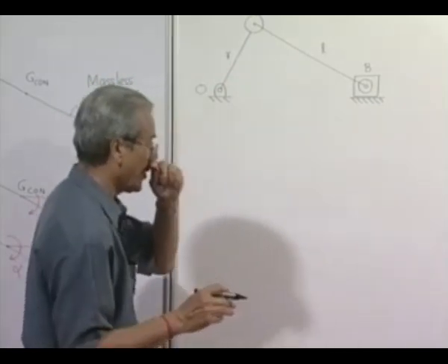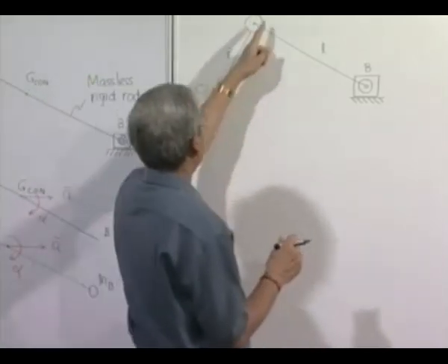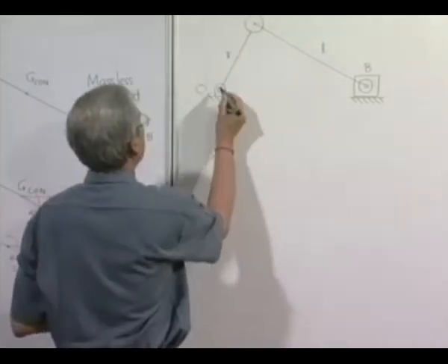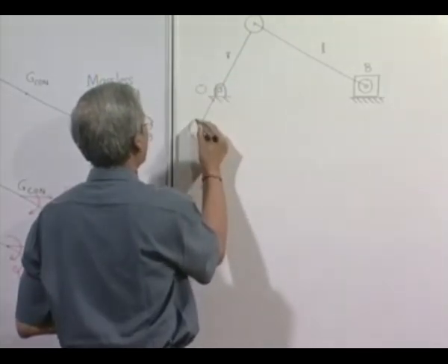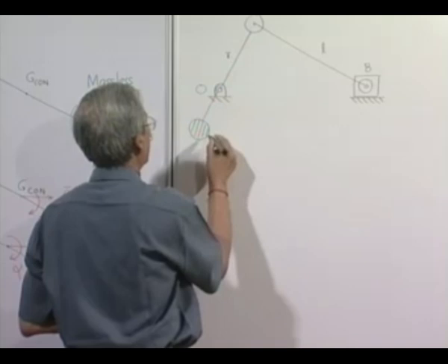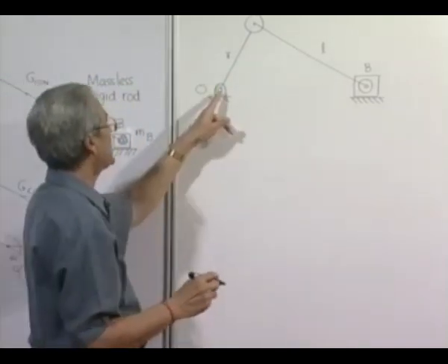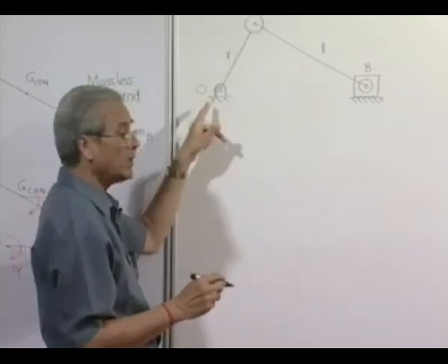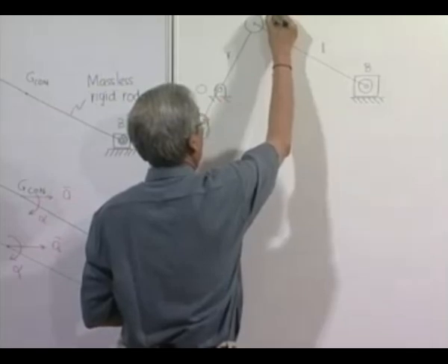From this point onwards, we should also keep in mind that the force produced by this purely rotating mass can be easily taken care of by placing a counterweight. So this counterweight placed at the opposite end of the crank will balance not only the original crank, but also the apportioned mass of the connecting rod, MA, here.